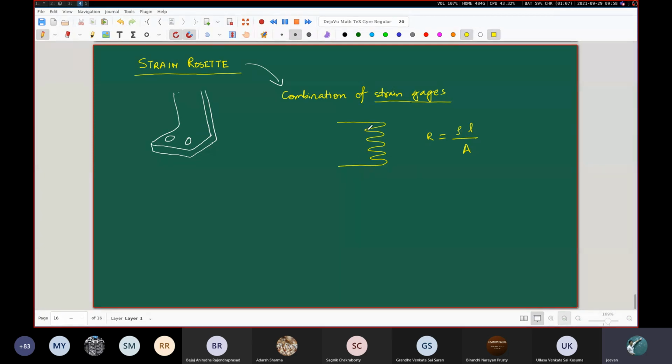Now, this is a strain gauge. Of course, it is not put like a wire hanging in air like this. It is put under a nice packaging, a very flat kind of structure, almost like a band-aid. Like a band-aid, you can put it on any machine part. These two ends can be connected to an electrical circuit. Not any kind of circuit, rather they can be made part of a Wheatstone bridge, which you are familiar with from your electrical technology studies and maybe even from high school physics.